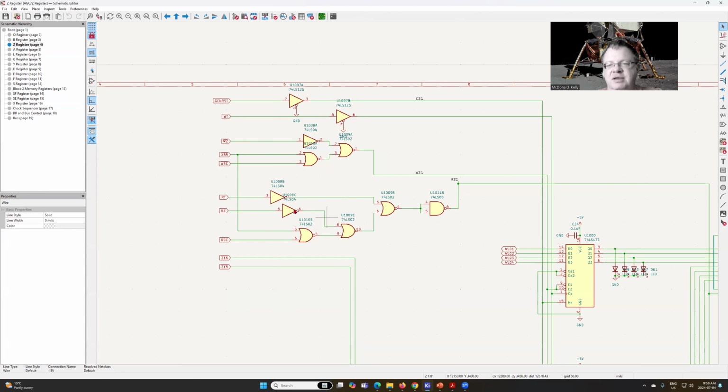So the circuitry here is basically exactly the same as this. But then we NOR it again with the write timer so that we'll only push data onto the bus when the write timer is asserted. And because we've added this extra NOR gate, we need to invert it to get it back to the negative enable logic we need for chip enable.